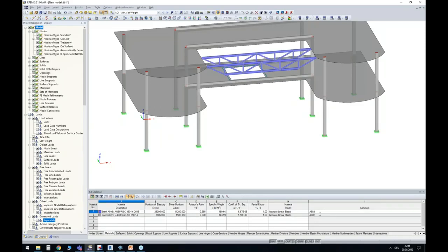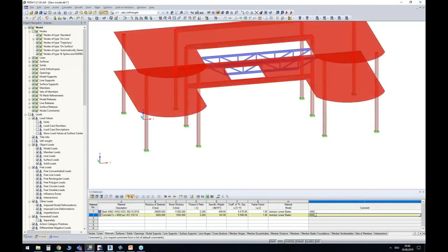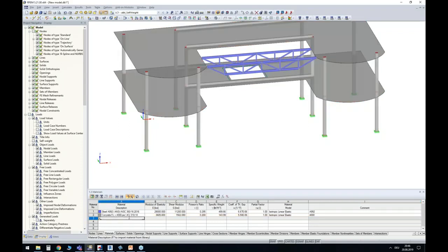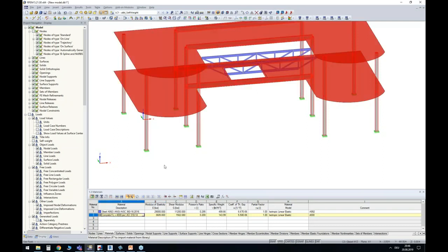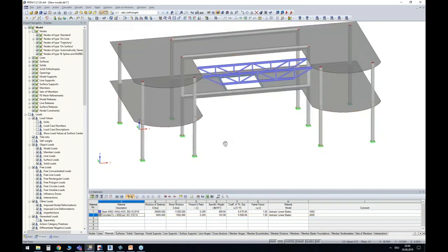You can see in Revit, the concrete that I'm using here, the concrete with 4,000 PSI, the name of that in Tekla is just 4,000. So if I would have imported only the pure name without the conversion tables, I wouldn't have gotten any value. So the conversion tables again help me to convert it correctly into a material from my library.